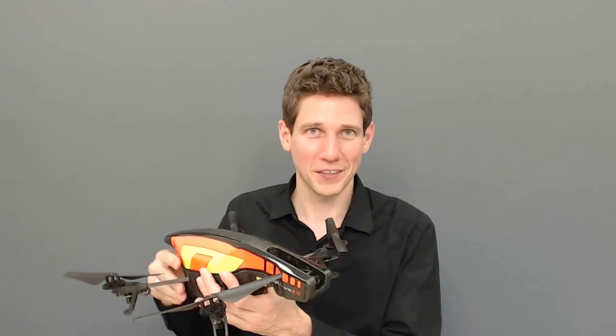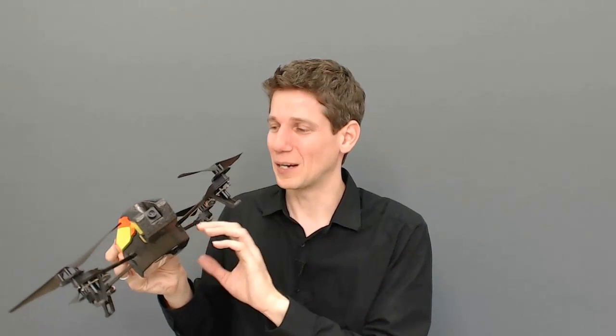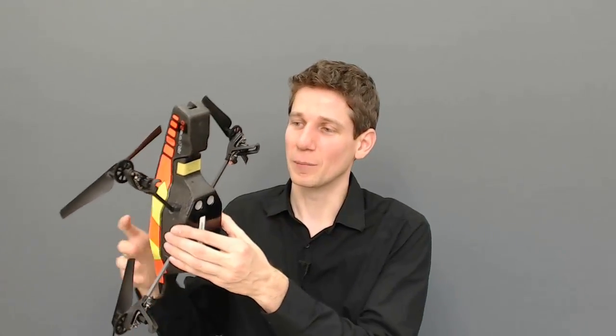The thing that makes it so cool for us is that it has a whole bunch of integrated sensors, and that it transmits all of the sensor data back over the wireless so that we can use it then on the computer. For example, it contains accelerometers and gyroscopes that it uses to estimate its attitude and to keep the quadrotor leveled. It also has an ultrasound sensor to measure the distance to the floor and then to keep the flying height of the quadrotor constant.